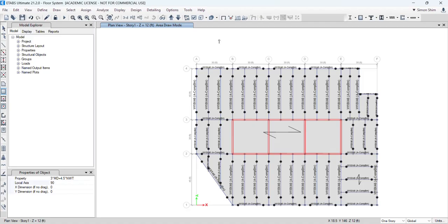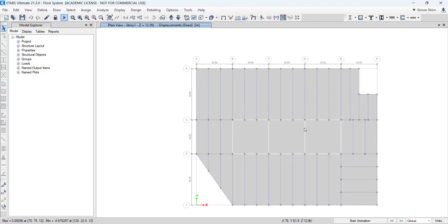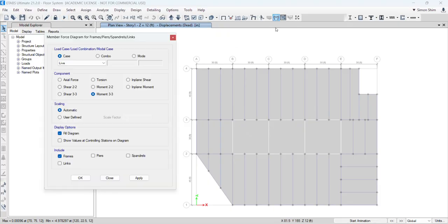So this is everything that you need to practice. No matter what building you are given, you should be able to draw all the columns, beams, girders, moment releases, and slab, draw the slab and boundary condition, assign the loading, and analyze it. And okay, let's run this model and see. Since I redrew the slab, I don't have any loading. We'll just check the self-weight deflection only.